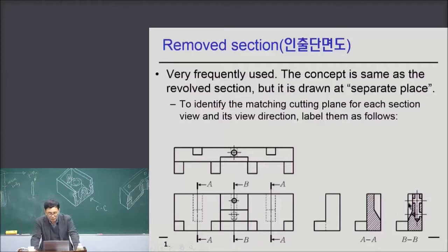So you see, looking at the removed section, there are so many flow channels crossed inside. Okay, right? BB, AA. And this is a partial view of this area only. A hidden line is added since this is a cut here. So the hidden line is here. Then you can make the drawing very clearly readable. So the hidden line is added. All right. This is a removed section.